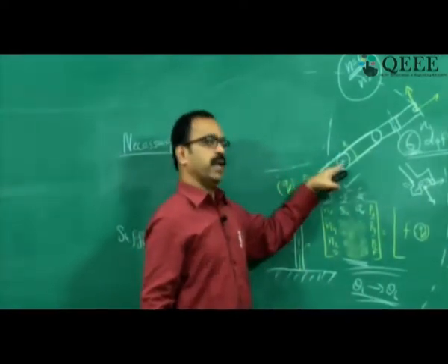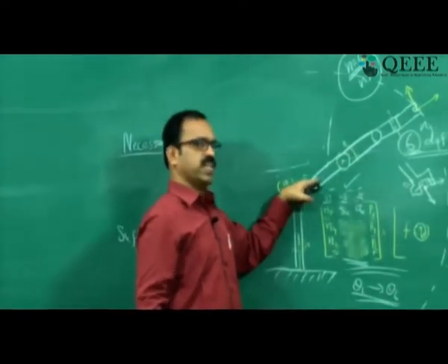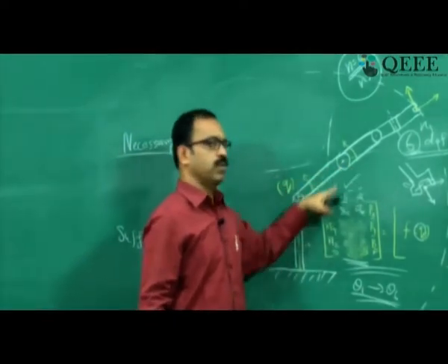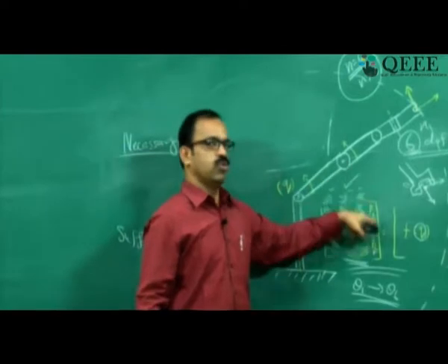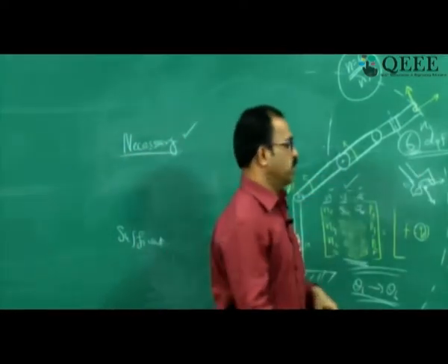And if you suggest a position or a tool position where the joint angle needs to travel 180 degrees, then the robot will not be able to get a solution for that because the joint limit will be violated. So that also should be taken into account when we consider the inverse solution.